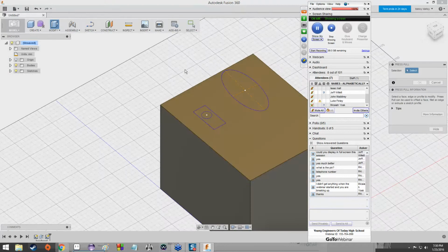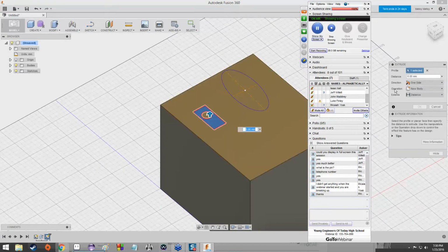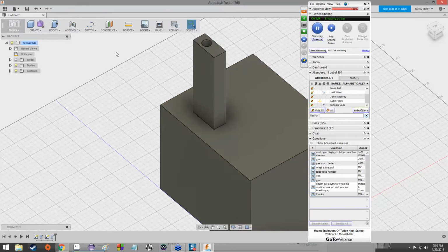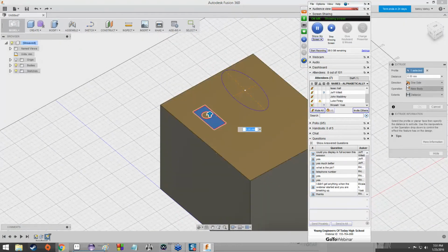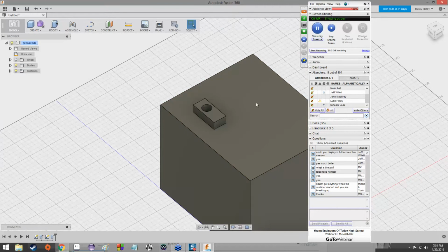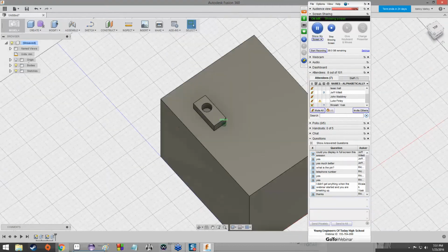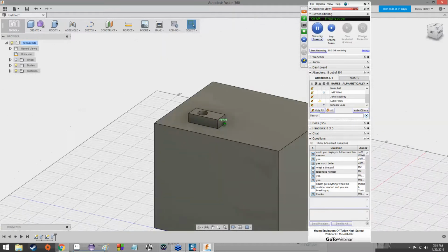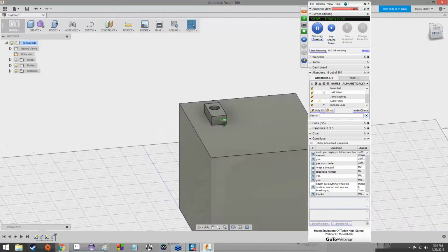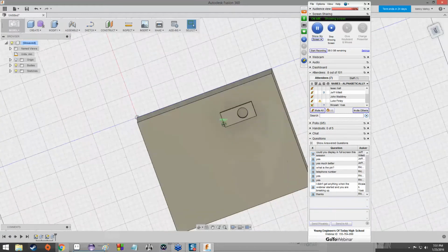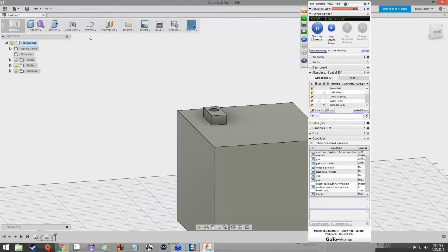Now what would happen, specifically, if I pressed pull on this? Let's extrude at 10 millimeters. I think I accidentally extruded 103. I think I hit a 3 at the last second. There we go. Now you'll notice that because we separated all that stuff out, it automatically just assumed that it's not something we wanted to extrude. So now we've got a more complex shape just by combining different two-dimensional shapes. And we can take this even further.